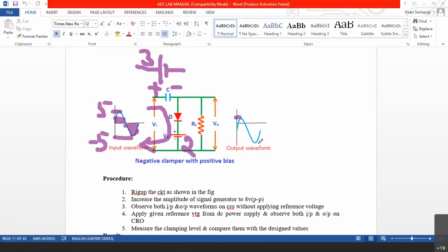If the signal goes down, can you now tell me how should I mark these two values? 2 and... 2 and -8. It is +5 minus 3, which is now 2, and here it is -5 minus 3, which is totally -8. Between +2 to -8, you can again see it is totally 10 volts peak to peak only.